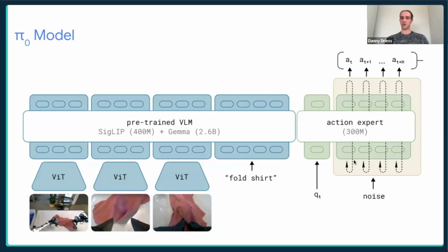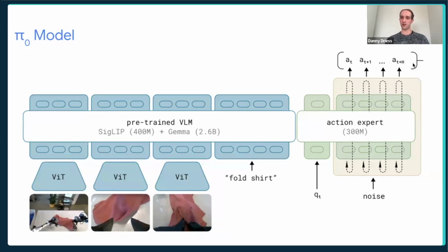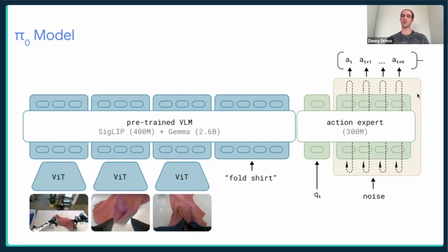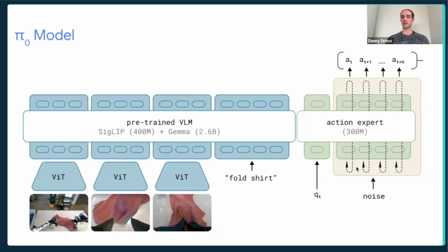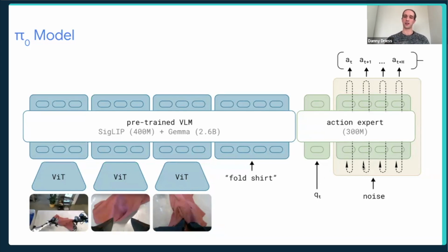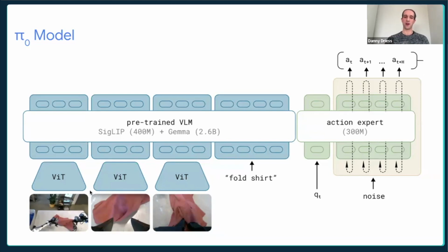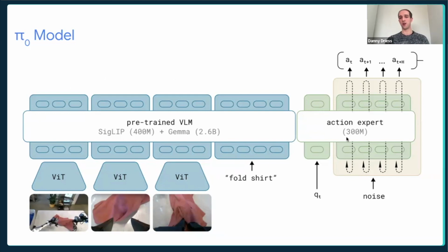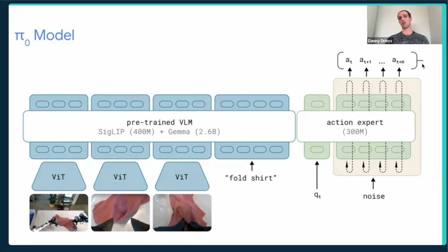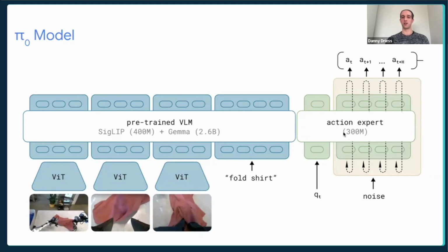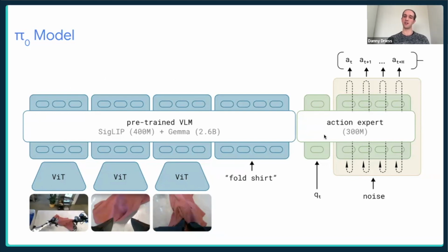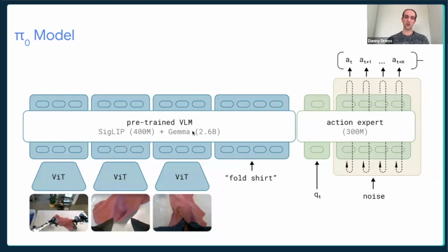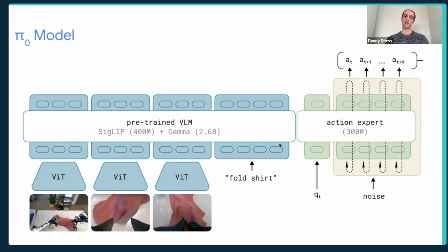And then what this action expert is doing is predicting a robot trajectory. So each of those A's here is a whole robot action, and so this is a whole robot trajectory. And this is being formulated as a flow matching objective. At inference time, we run one forward pass through the backbone, and now we denoise noisy actions to get a robot trajectory, and this is run in a loop. We do 10 denoising steps, and this action expert attends to all those tokens in the backbone.